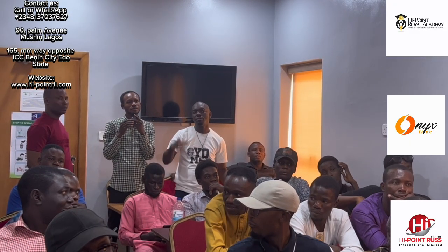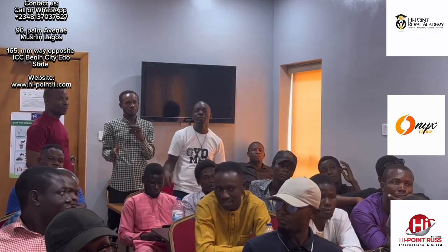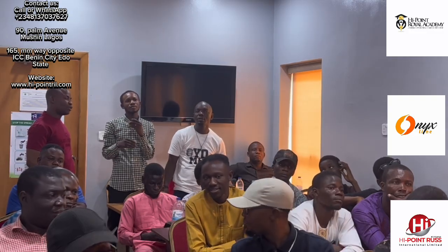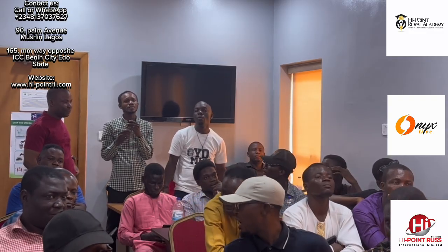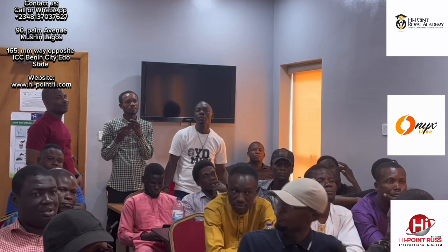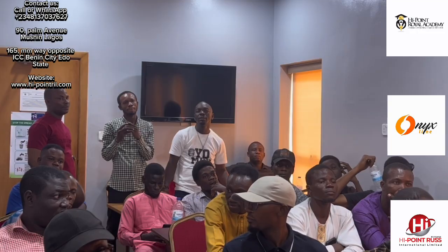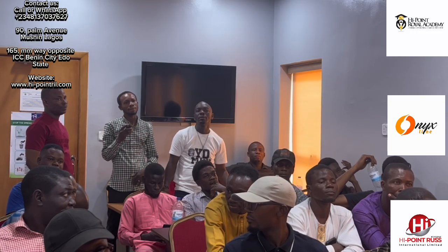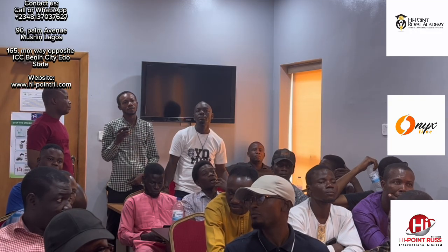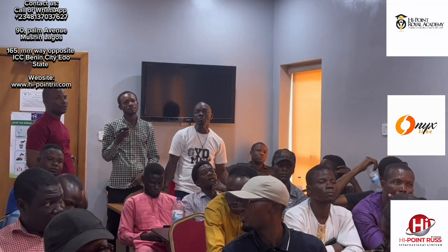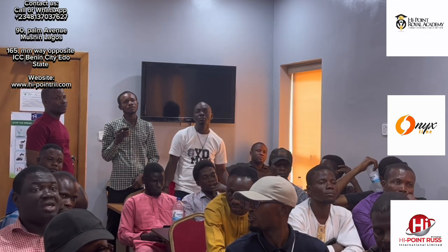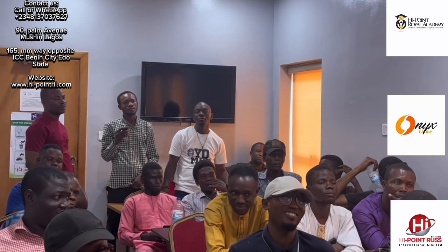It's just the battery, your normal battery terminal connected to it only, and then the fact that it has a lithium wake up function, that's where it really stands out. That lithium battery is the kind of battery that if you drain it to the end, most times it's hard to use a normal battery charger to charge it up, to wake it up. Or sometimes